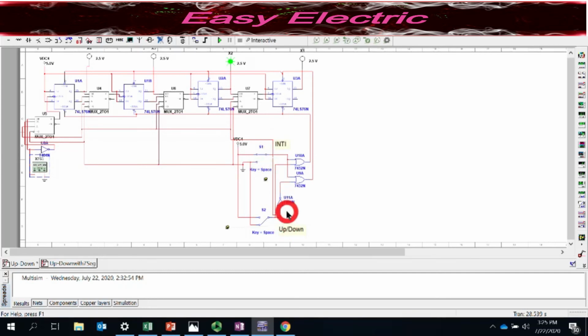So see how it works. If you put this switch down, it is connected to 0, and this one is connected to 1. Right now it is connected to 0, so that means it should count up, right? Then I need to initialize, right? So here you just initialize that. First I need to start the simulation. So see, this is here, which is the 0. It should go up counter, and I initialize for a short time. It loads 0, and now it's back to 1.